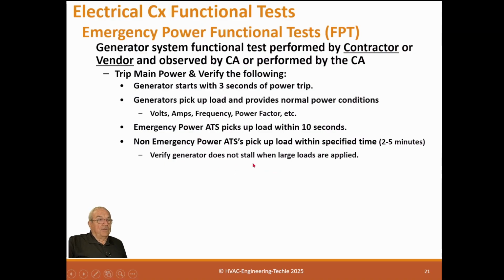Verify the generator does not stall when large loads are applied. So one of the tests they do is when the generator is running on a normal load, they go to the load bank and pop a bunch more load bank on to see what happens if it stalls under the load. I don't remember offhand what the conditions are for the loading, but we can do that. It simulates an ATS coming on.